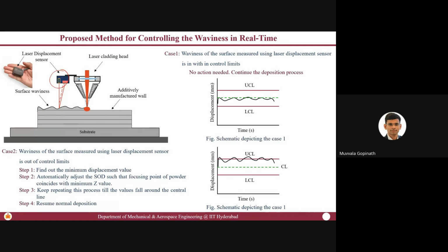Yes. For these reactive materials, we typically use a vacuum chamber. Again, the domains of application are entirely different. When we talk about titanium and titanium-based alloys, especially for implants and other things, we do it in two methods. One is a controlled atmosphere. In the powder bed fusion process, you take care of the ppm level of oxygen. If you can control the ppm level of oxygen, you will be able to deposit a component without much oxidation. That is one. You need not go into the vacuum.